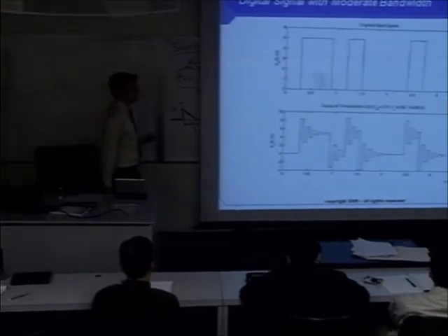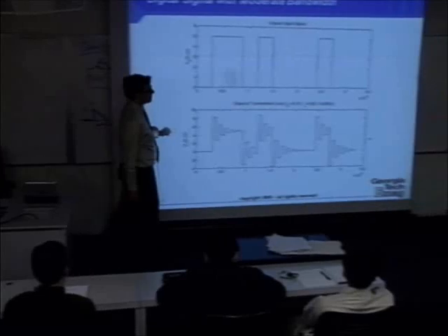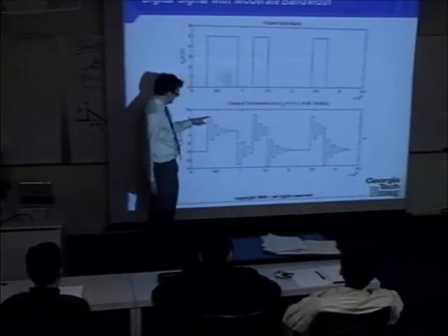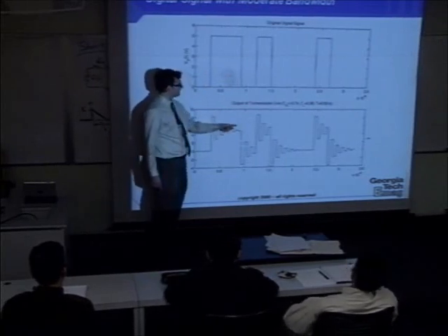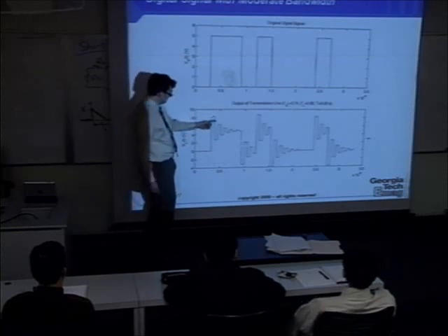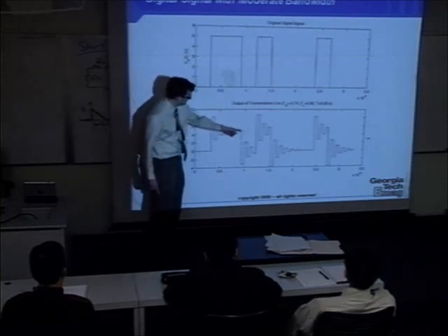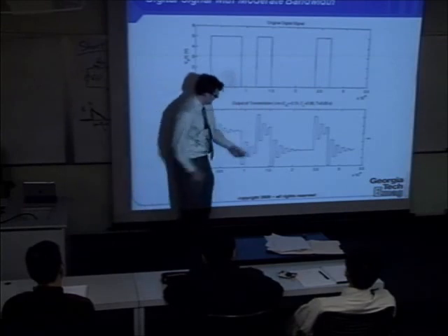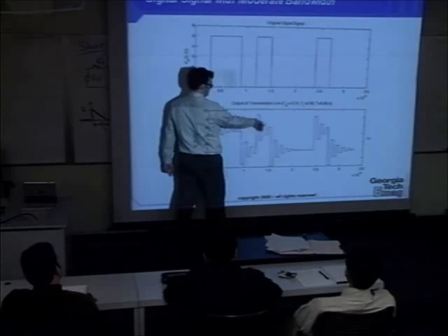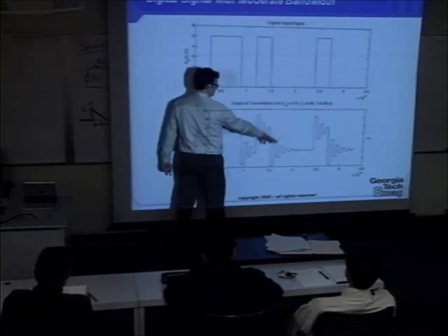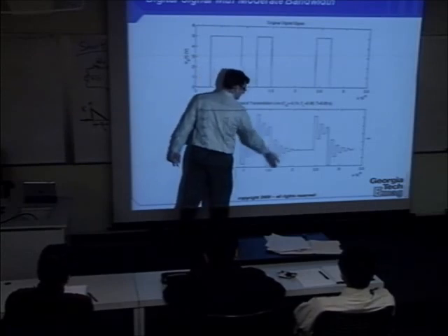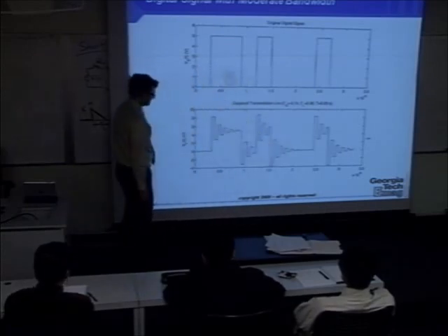Now let's shorten the pulse up. Now we're looking at pulses that are less than 1 microsecond. And you can see that the ringing occurs now at a scale that kind of distorts things. I'm getting ringing that occurs all the way to the end of my first pulse here. So here's for example 1 bit, and I've got to jump up, jump down, jump up, jump down, jump up, and it's still not settling until when you make the next state change in that scenario.